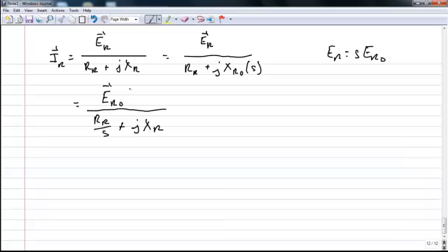So what is this getting us? Well, the point here is that the rotor effects that result from the varying speed, or the relative velocity between the rotor and the stator, can be modeled as a varying impedance with a constant source, E_R0. So instead of making the voltage frequency change, I'm modeling it as a varying impedance with a constant supply.